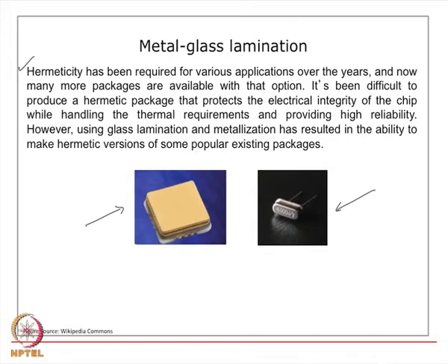But in hermetic sealing, this is not allowed. The die and the first level interconnects are completely sealed, checked for airtight sealing after the process is over, and it definitely could be expensive compared to the normal plastic encapsulation or a ceramic encapsulation. Now, it is difficult to produce a hermetic package because of the cost involved and the test involved, but it